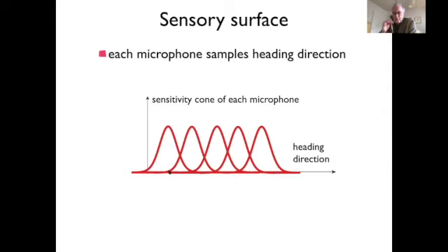A lot of modern microphones, like the one I'm using, have very broad characteristic, which is sort of desirable, so that it can actually pick up my voice independent of exactly where the microphone is. Other microphones are more directionally sensitive for certain purposes. Those were directionally sensitive, had a cone where they were most sensitive to sounds that were within about plus minus 30 degrees, sort of like a 60-degree angular cone, caused by the mechanical properties, which was on purpose for us, because that meant that if there's a sound source in front of the vehicle, then only those microphones will react strongly to it that are somewhat pointing in the direction of that sound source.